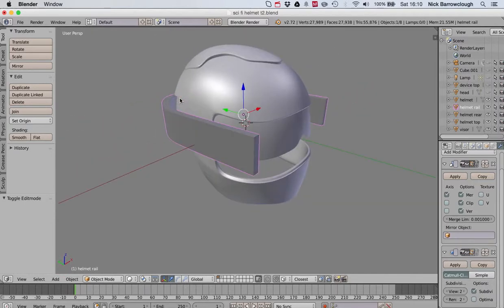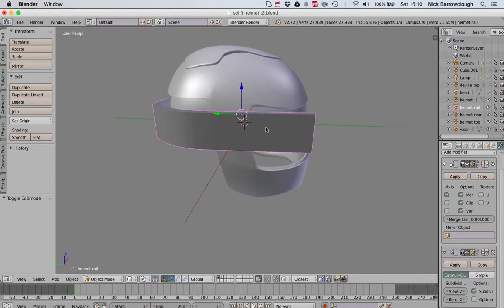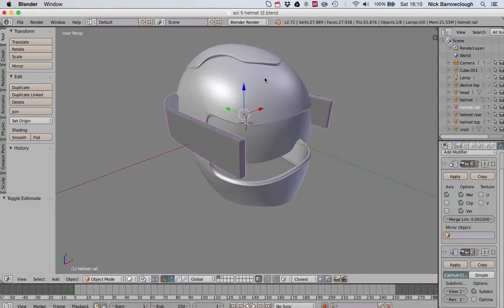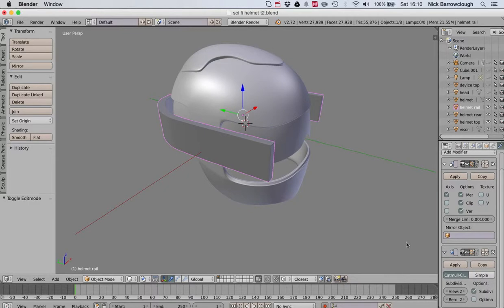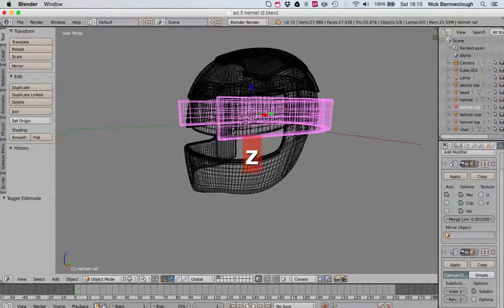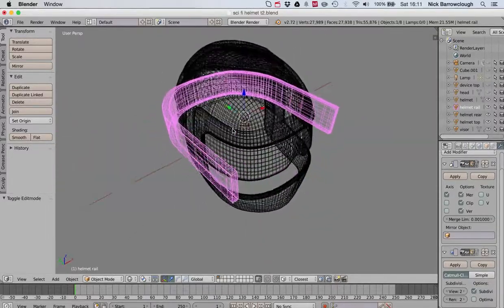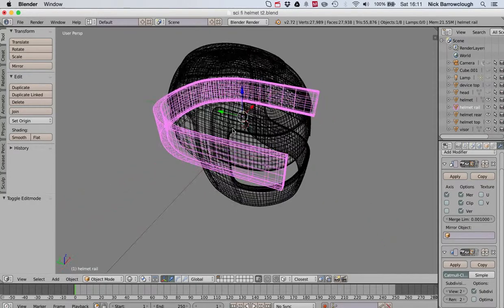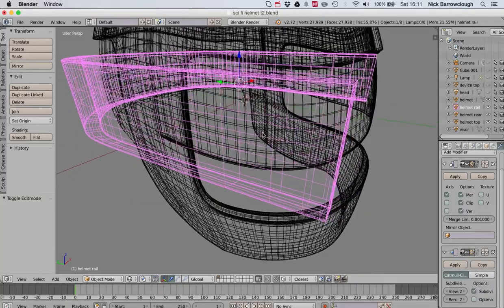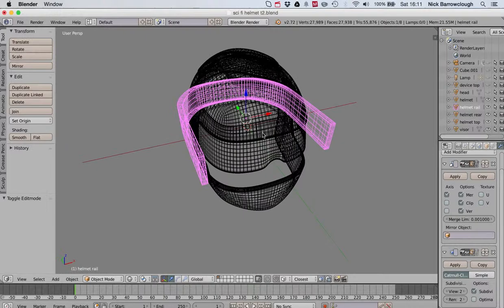We continue in the same basic method, creating these pieces where we extrude them from flat parts or from sections of our base helmet. And this method is keeping our mesh pretty standardized, so it's going to be relatively easy to UV map this later, because we haven't really got any funky subdivisions and polygons in there, so we may not even need to retopologize it.